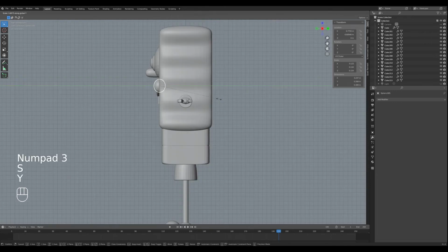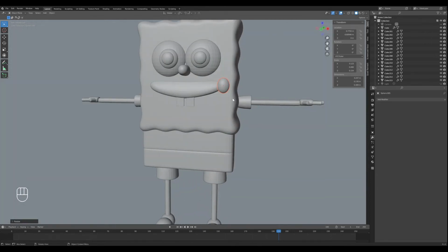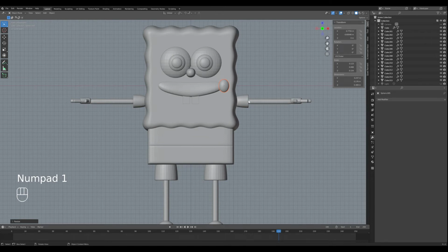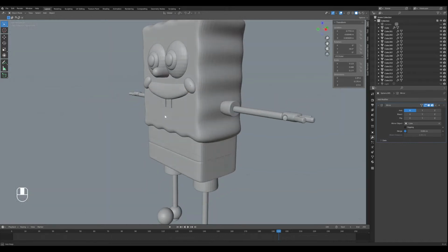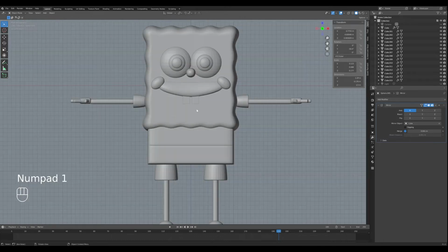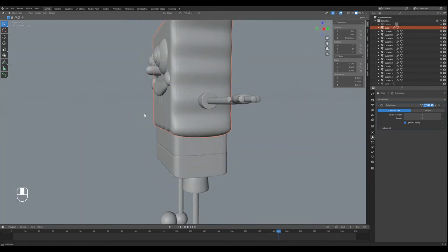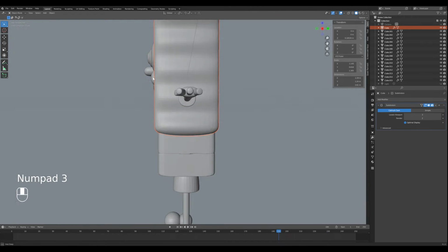Okay. And then let's scale along the Y to make it a little flatter. Okay, and then we're gonna rotate along the Y-axis like this. Bring it up. How about that? Okay, so we're gonna mirror across because we need it on the other side of his mouth. So mirror modifier, mirror object, click body, and there we have it. Okay, that'll work for now. Let's go ahead and do his chin. Make sure nothing's sticking out too much.